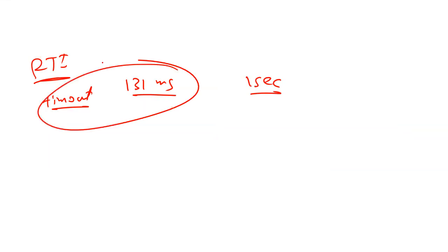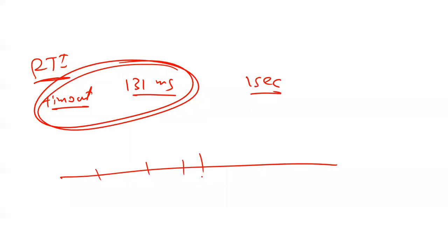I have to respect this limit. I have no choice. So what I did, I had interrupts every 131 milliseconds, and then I counted. Interrupt number 1, do nothing. Interrupt number 2, do nothing. Until interrupt number 8, because at interrupt 8, I actually make 1 second. Is that okay? I'm gonna use the same idea right now.